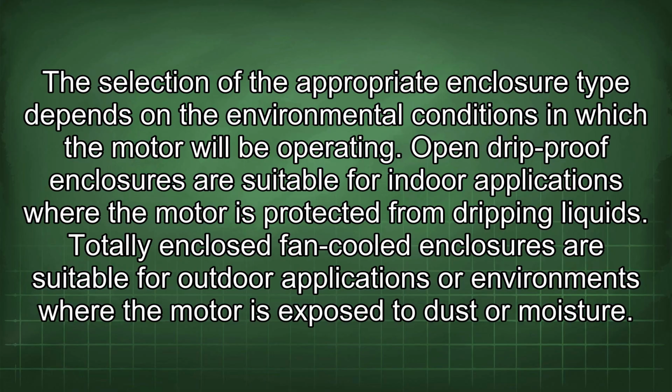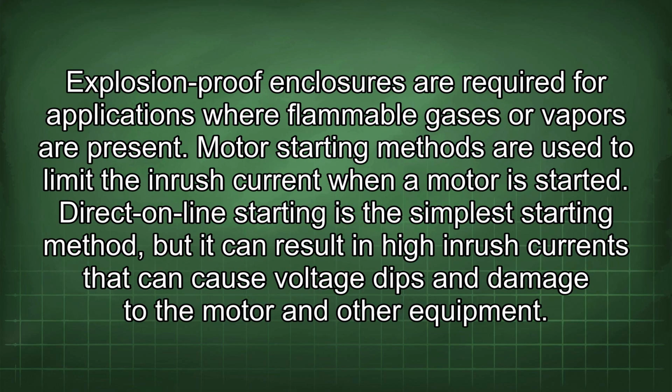Open drip-proof enclosures are suitable for indoor applications where the motor is protected from dripping liquids. Totally enclosed fan-cooled enclosures are suitable for outdoor applications or environments where the motor is exposed to dust or moisture. Explosion-proof enclosures are required for applications where flammable gases or vapors are present.